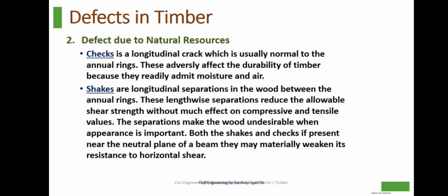The separation makes the wood unsuitable when appearance is important. Both the shakes and checks, if present near the natural neutral plane of a beam, may materially weaken its resistance to horizontal shear.